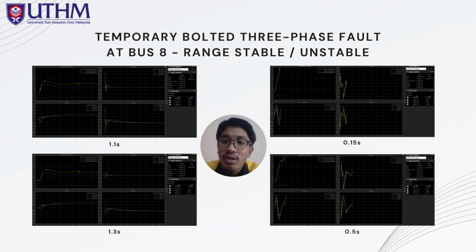So in the graph, we can see initially the system has a fault or short circuit happening in the system, and then after 1 second to 6 seconds, the PSS is stabilizing the system from the faulty condition to steady state conditions.